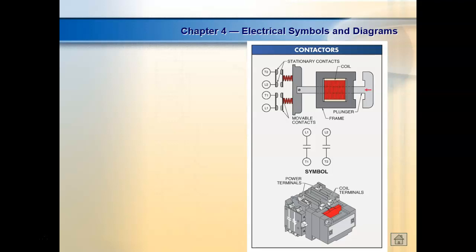By the way, a relay that's designed to run on AC, if you ran it on DC, it would burn up, because the AC depends on a little thing we touched on a little bit, called inductive reactance, which is how inductors set up opposition depending on the number of turns and everything. A relay that's designed for AC, put on DC, you're going to have almost a short circuit. A DC coil gets its resistance from a lot of wire. So if you take a DC relay and try to energize it with AC, it won't work because it'll have so much inductive reactance, you'll never get any current through it.